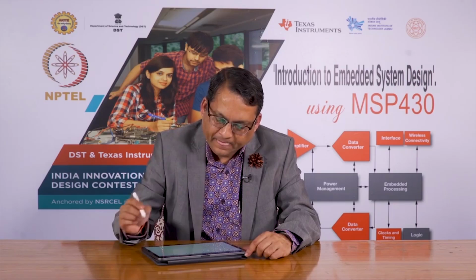And so, in this lecture we have seen how you can control external LEDs in a multiplexed fashion using the Charlieplexed fashion, how you can control large amounts of current through loads such as LEDs or relays using a low side switch or a high side switch, how you can also have a combination of high side switching and low side switching using the topology called H bridge, which is used to control DC motors and such loads.